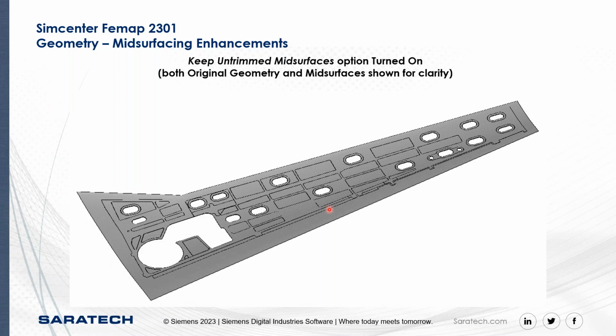For the untrimmed mid surfaces, you can see the original geometry there, and then also the mid surface that was created. They're both shown for clarity here. So the mid surface was created, but it was not trimmed if that option is turned on. This can be beneficial when you're attempting to connect the auto-generated mid surface to neighboring portions of the model. That can sometimes be a little tricky when you go through some of the mid surfacing commands. So this does leave it untrimmed, as shown here.